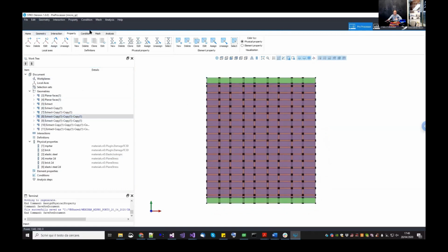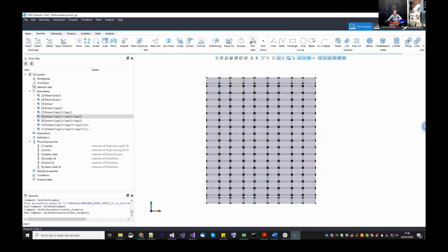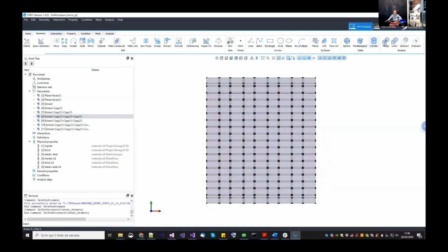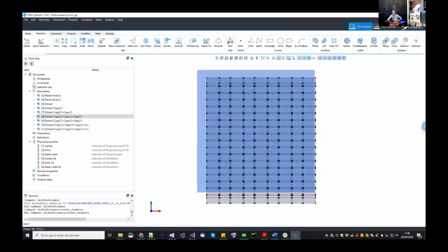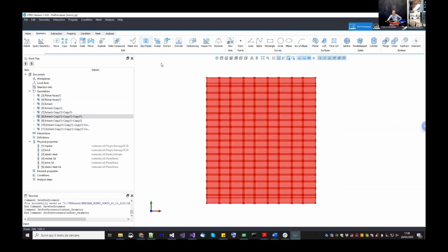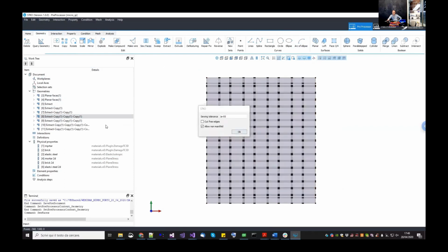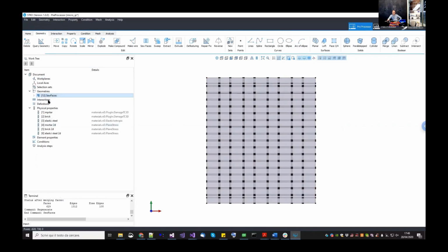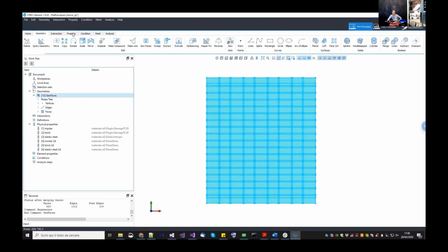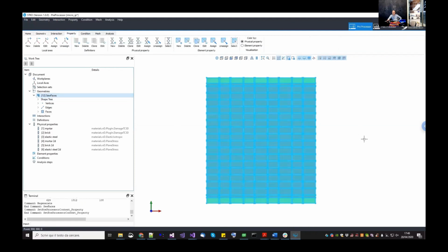So since they are all faces, when you have to do a Boolean operation, you can either go to the generic Boolean operation here, which is called merge, or you can use, in this specific case where everything is a face, the SU faces, which is a simplified Boolean operation made for faces. Okay, so I can select them all. I do SU faces. Okay, and then what I obtain is a single geometry, and the nice thing is that the properties are retained.